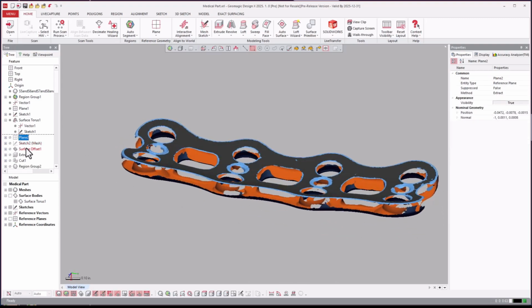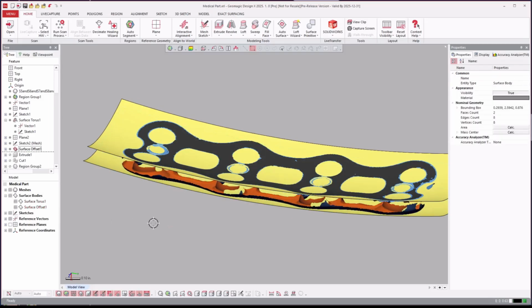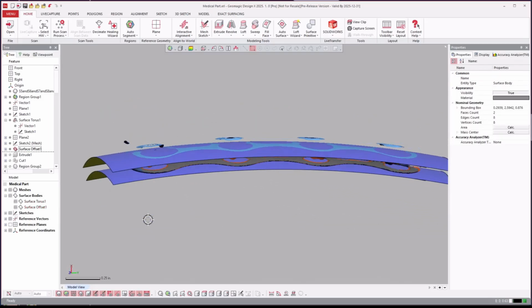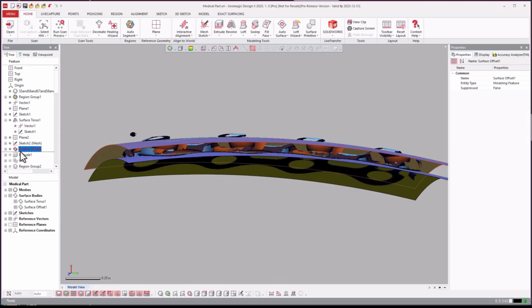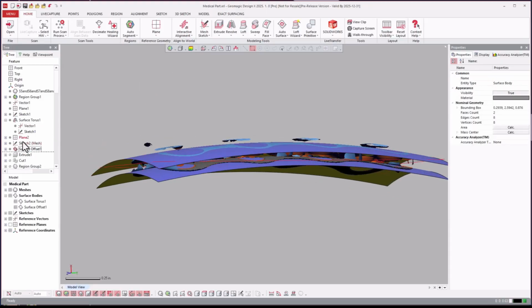And then we go into an offset surface. We'll turn our surfaces back on and toggle that other surface. We went ahead, it's a constant thickness, and it validated that it is by offsetting it. And you see here that you can double click on it and see a 0.1 offset value there.